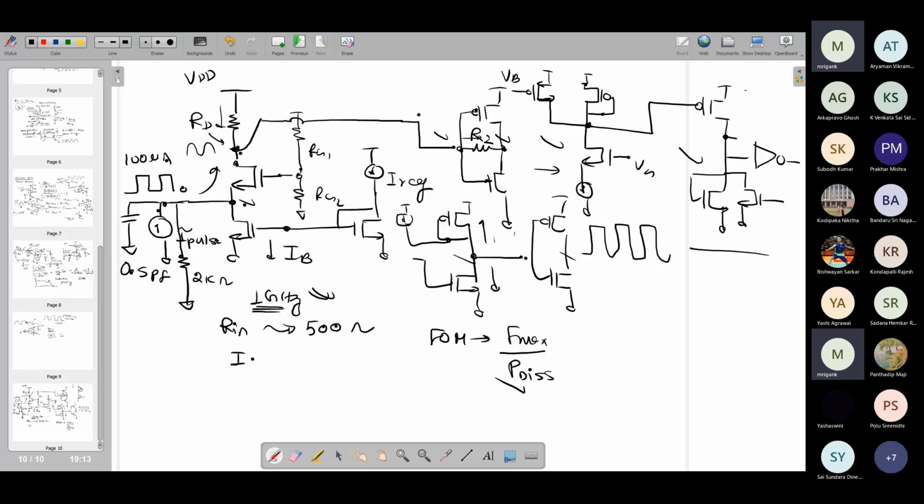This one is easier because you know that the bias point of this stage will be determined by the PMOS, and then for the next stage, anyway, I need to use PMOS as the input device. And here you can find out what is the value of bias current to be used, what is the current I should use for diverting into this current source, what should be the current going into the direct connected one, and what should be the gm of the direct connected one. This is what you can look at.